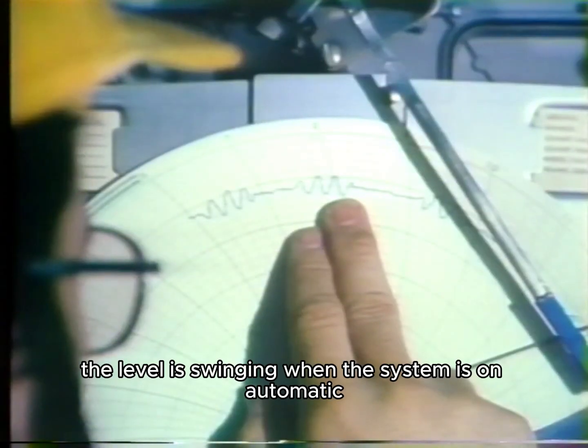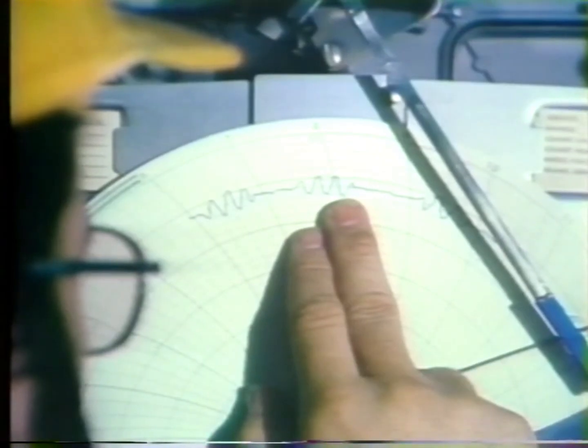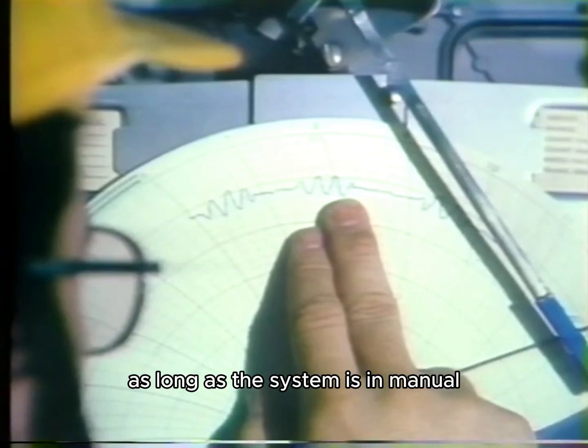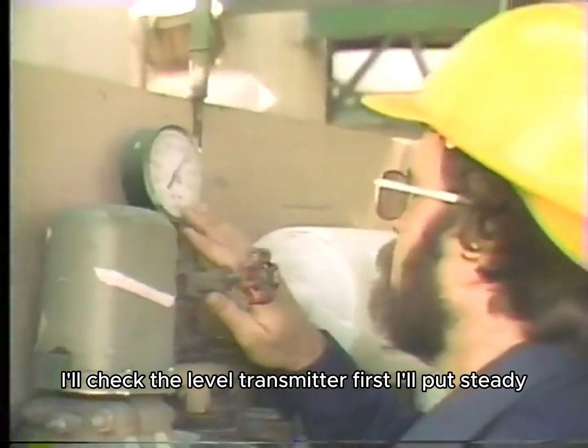The level is swinging when the system is on automatic, but in manual, the level settles out. As long as the system is in manual, I'll check the level transmitter first. The output's steady.